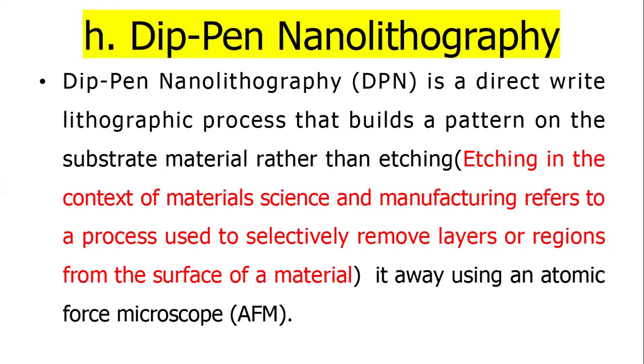Dip pen nanolithography. Dip pen nanolithography is a direct lithography process that builds a pattern on the substrate material rather than etching it away, using the atomic force microscope.